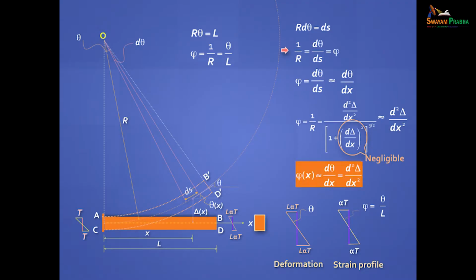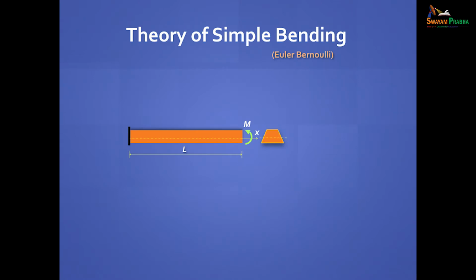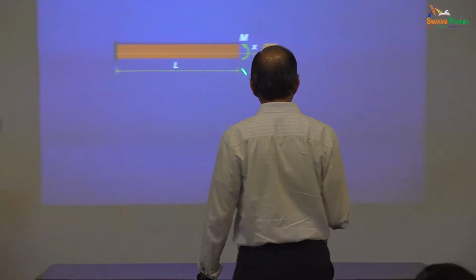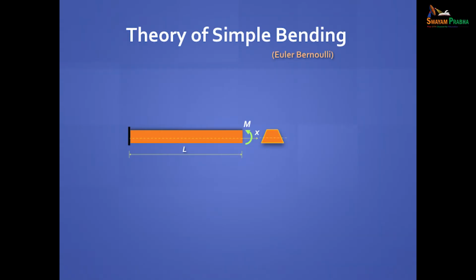No bending moment or shear force in this derivation so far. So that's it, you're familiar with this. Now we take the same beam and apply the moment. Now we'll try to generalize and say the section need not be a rectangular section, but it has to be a prismatic section for our definition here. Let's give it a trapezoidal shape. The cross section everywhere is this trapezium, which means the centroidal axis is not in the middle. In the previous case it was in the middle.